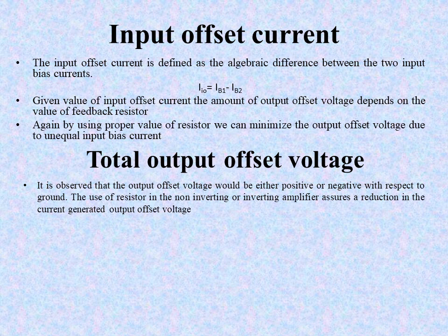Suppose you are running some application of the operational amplifier, like an adder circuit or integrator circuit. We make the basic circuit, but we should always remember to add these two components also, the potentiometer and this compensating resistor, in order to reduce the effect of output offset voltage.